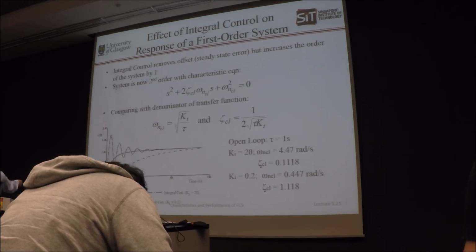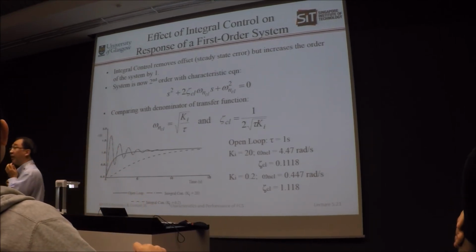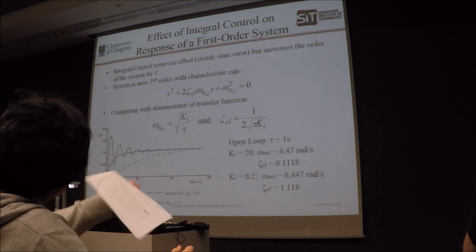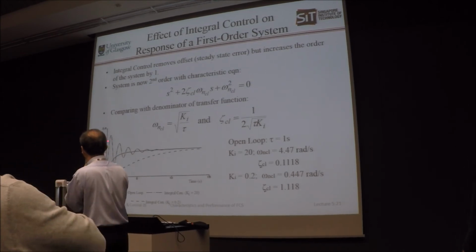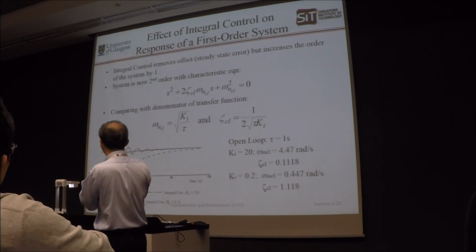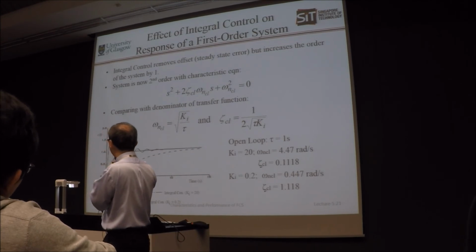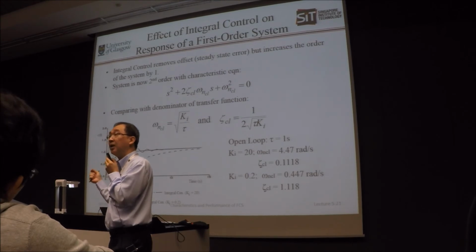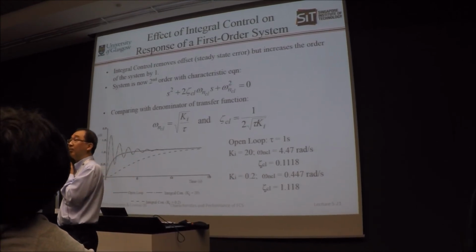Whereas with this one, the door is going to slam, because the moment you let go, bump, it comes back very far, and then you overshoot. Of course your door cannot swing inside, so it will just hit the door frame and give you a loud bang. But typically what you see here is a situation where your damping is very, very small. You have very high overshoot, what you call 60-70% overshoot. Typically in your feedback control system design, this is undesirable.